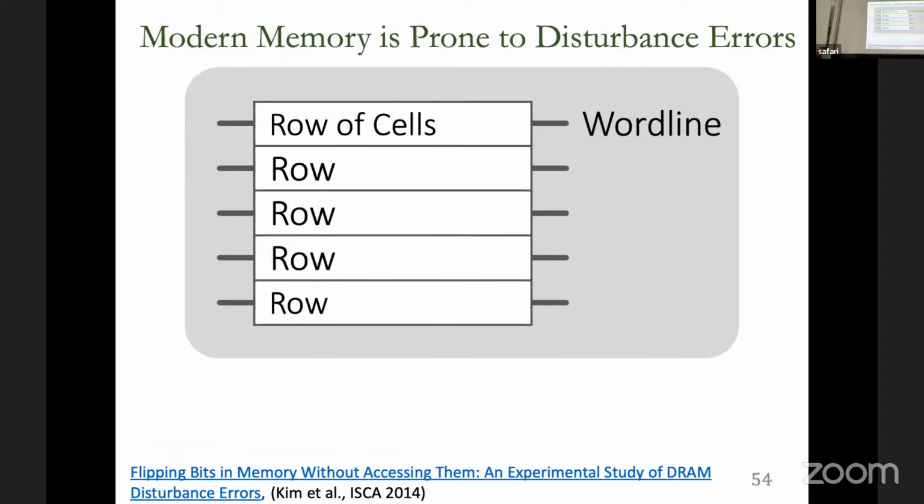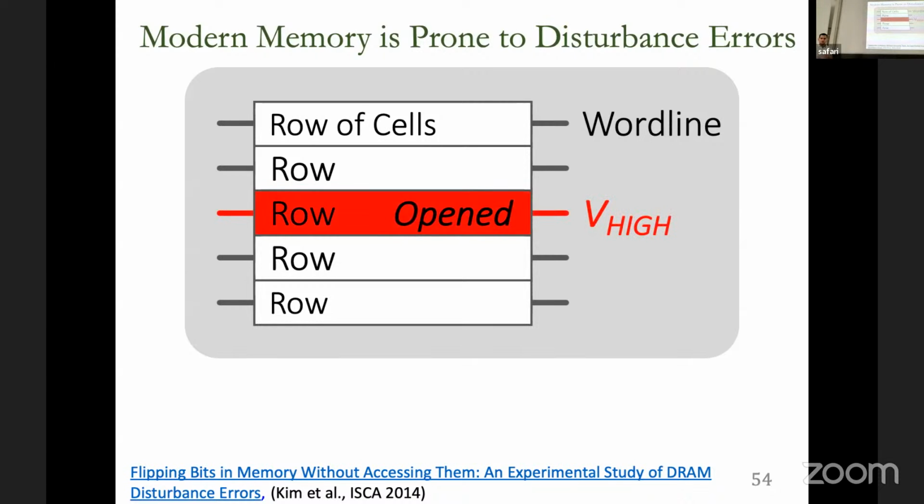So the way that this is done, in the memory chip, we have several DRAM rows inside the DRAM array itself. One of the rows stores your data, and the operation that you do to read the data from the DRAM chip is called activation, or the opening of that row.